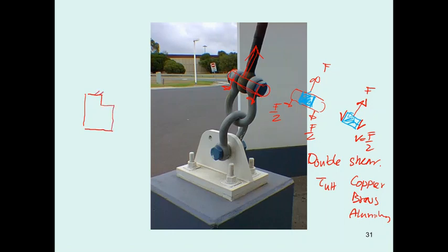We're going to put wood into the machine and fix it around here and put the force into the wood here. And then what happens is the force will shear it, and it's going to have a crack in this direction. This portion of the wood will be subjected to the shear force here. So if the force is F, the shear force is going to be F. This one we call single shear. So we're going to test our specimens, both double shear for metal and single shear for wood parallel to grain, in this material testing.